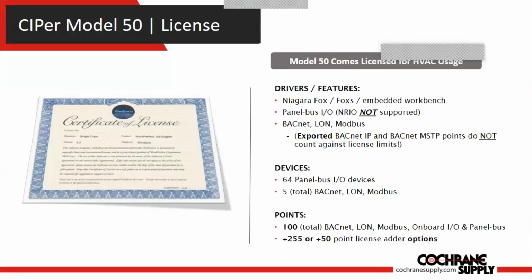In terms of the drivers and features that the license provides you, it provides you with the Niagara Fox as well as Fox S, which is the secure encrypted controller to controller and controller to supervisor protocol, and embedded workbench. Also provides the panel bus I/O module support, BACnet, LAN, and Modbus drivers. And just want to make mention here, and there's a note, the BACnet IP as well as the BACnet MSTP points do not count against your license limits.